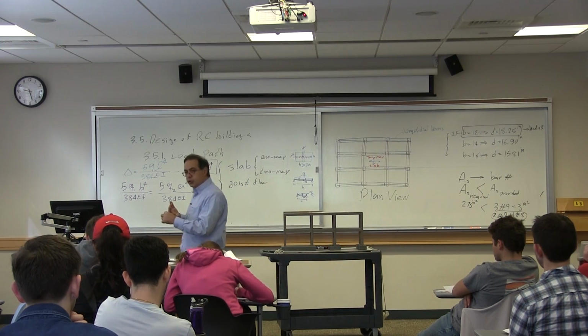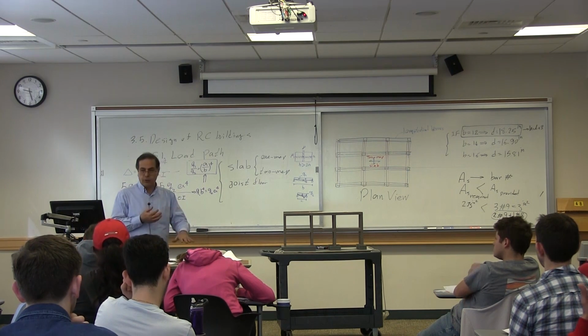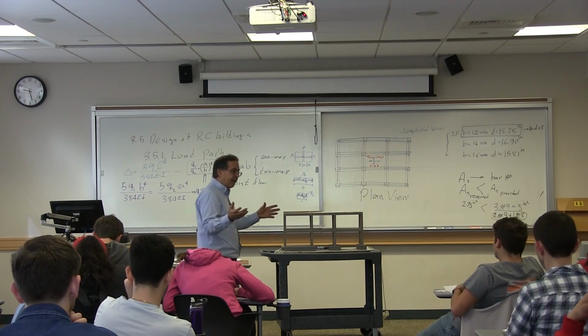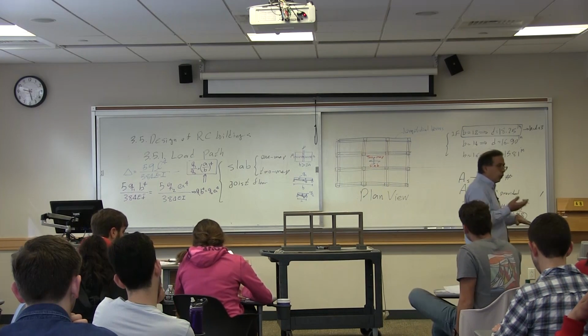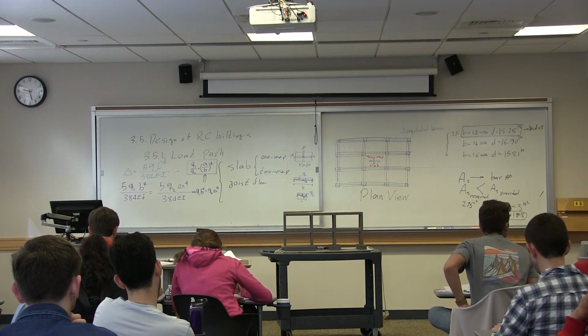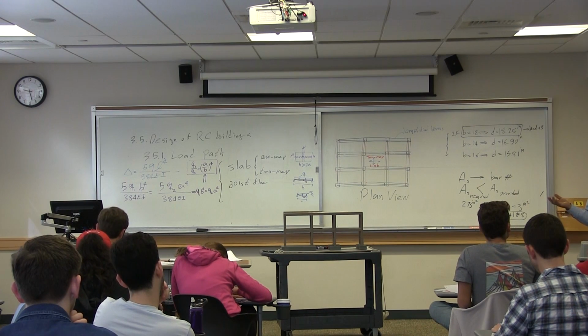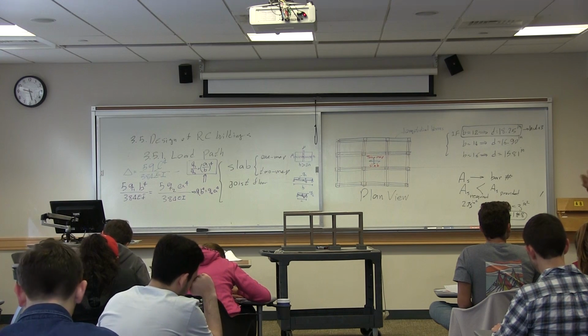Dead loads in a structure, the primary source of dead load is the floor system. If you want to find which element is the heaviest, the answer is the floor system. So if you don't know the weight of the floor, again, your calculation could be incorrect. The weight of a joist floor system is different from the weight of a slab system.